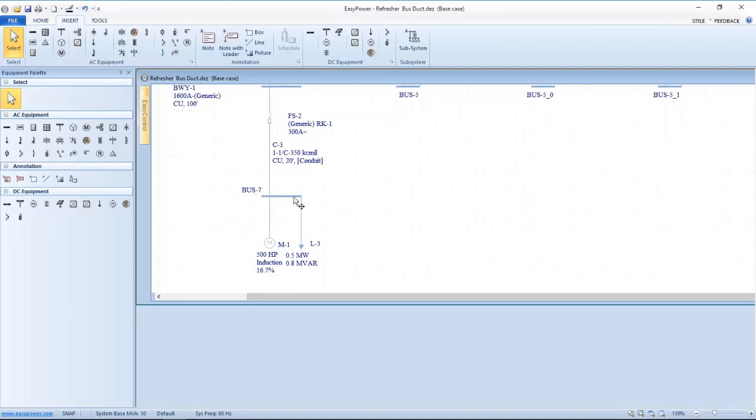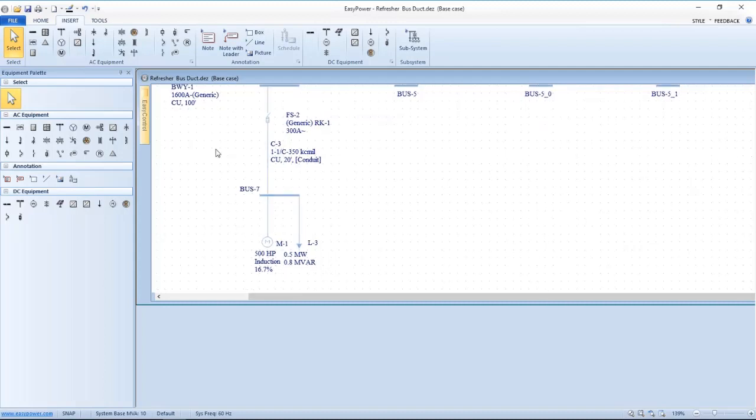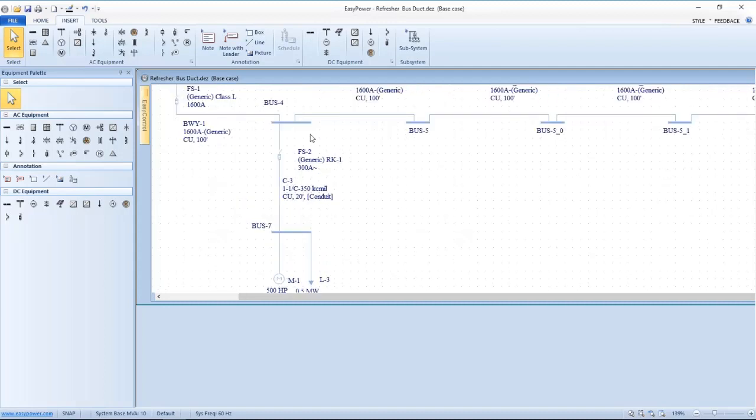So the fact is, even though we're averaging the lumps out here, the possibility of a fault at any individual load is much greater than it would be on the whole total. And so again, as the person doing the analysis, the size of this particular protective device, when I'm thinking about worst case, isn't going to be the sum of the total. It'll actually be the largest one that's coming off of this particular drop.